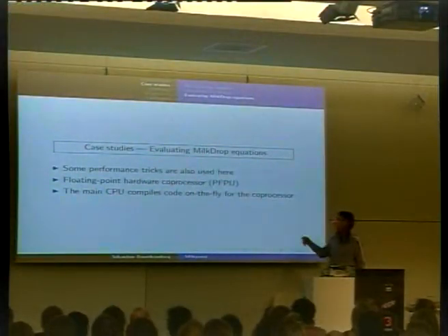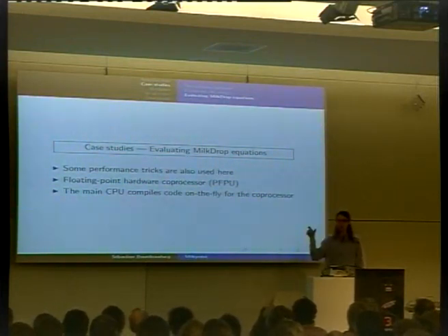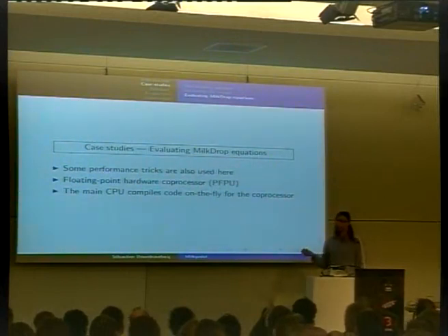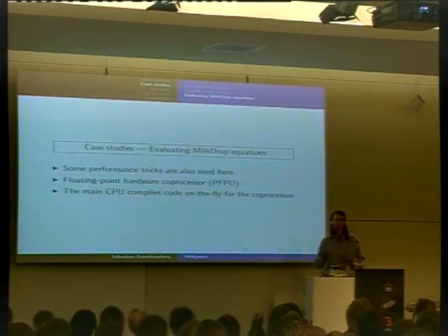I'm not going to explain a lot into the details, but basically you have several floating point pipelines and a very low-level instruction set which says put that into the pipeline and fetch that from the pipeline. And the compiler needs then to schedule all the pipelines by itself. By doing that, first you remove the need for a scheduler inside the hardware because all the scheduling is done statically in the instructions. And also the compiler is able to extract a lot of parallelism from the computation which needs to be done. And this gets a very fast system.